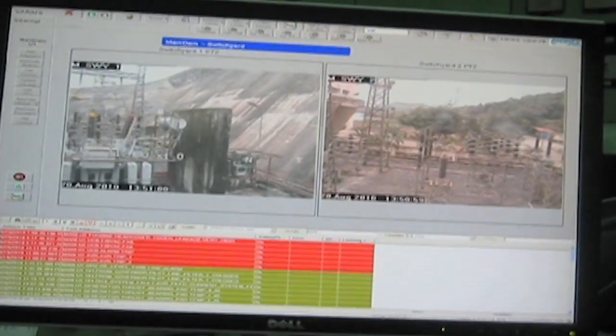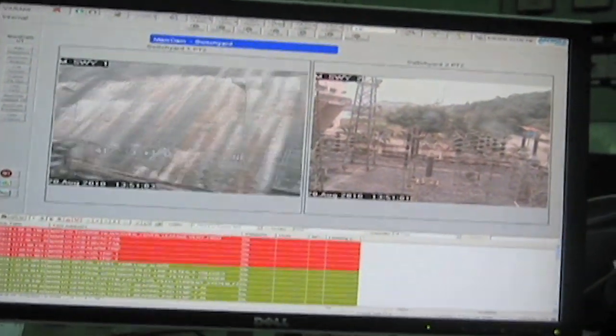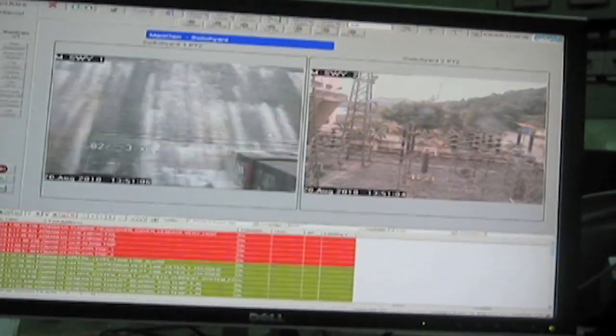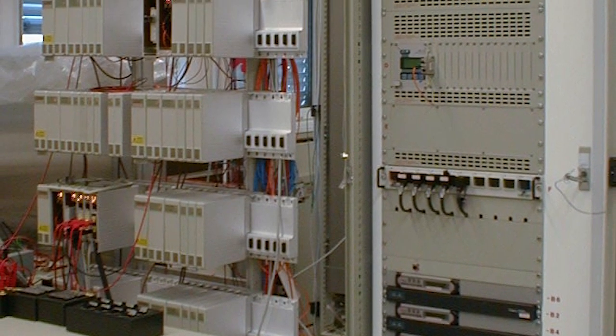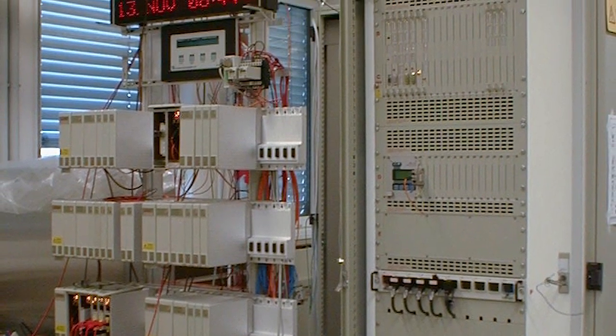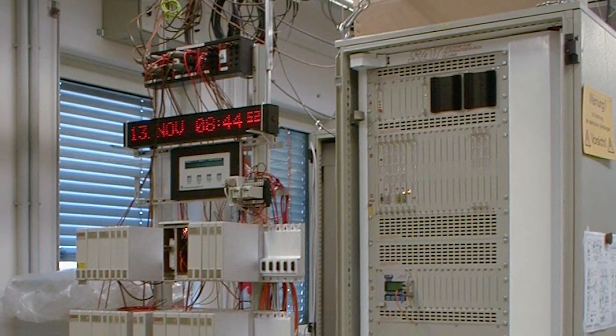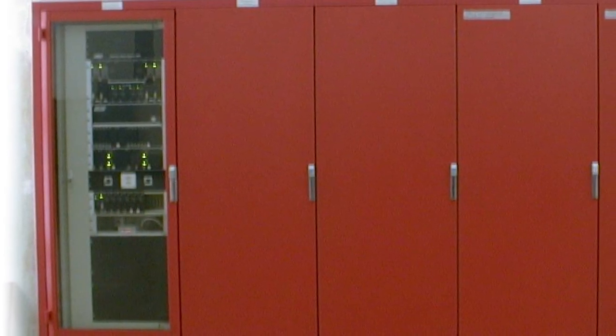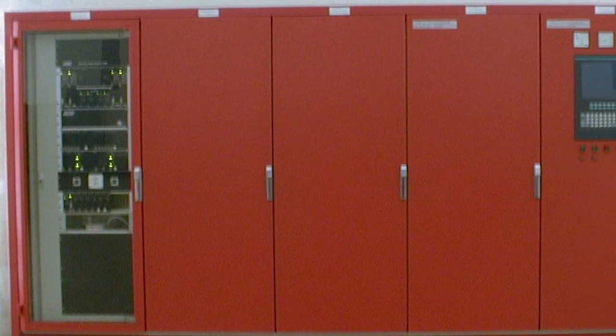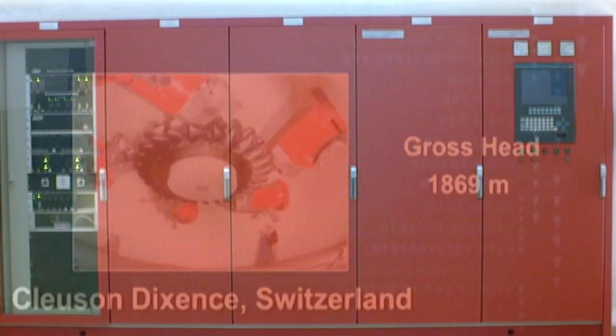Control system. They are necessary to facilitate the automatic or manual operation of the generating unit. Functions include start-stop sequencing from standstill to grid operation of the generating unit, including all the auxiliaries of plant, gate control, switch yard control, station service auxiliary control, etc. There are a variety of inputs for various signals or parameters, and control is based on the logic designed in the microprocessor-based controller utilizing these inputs.